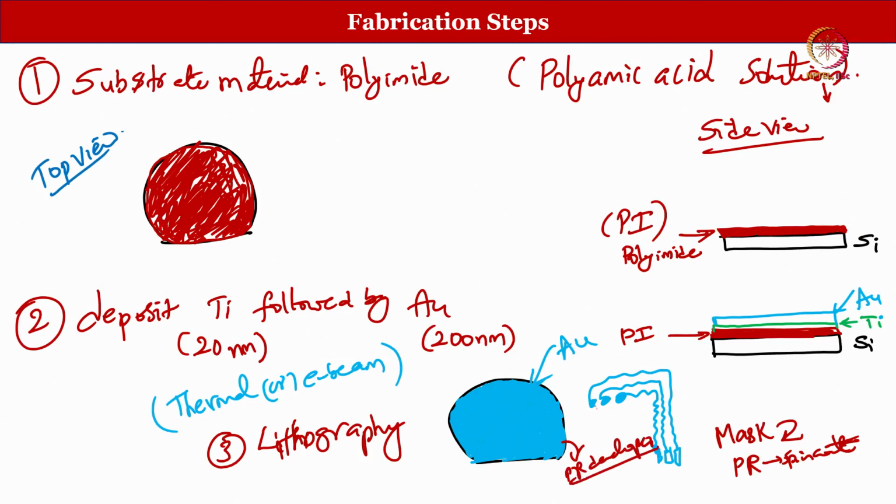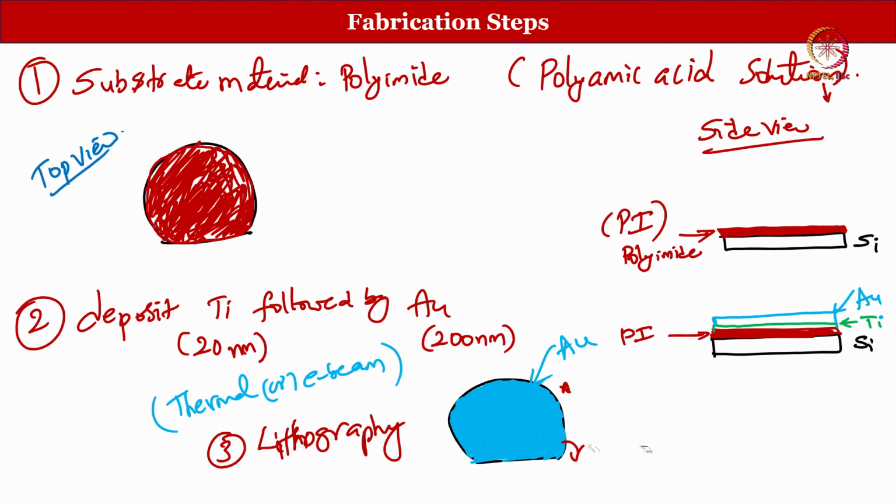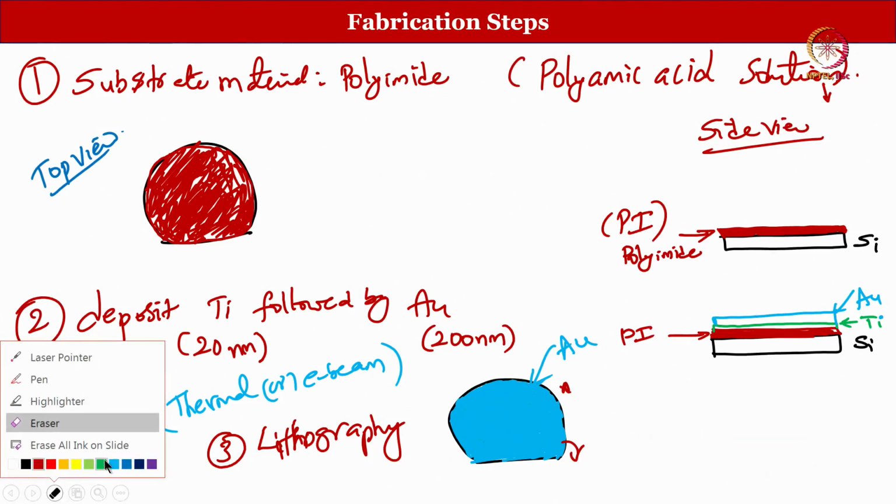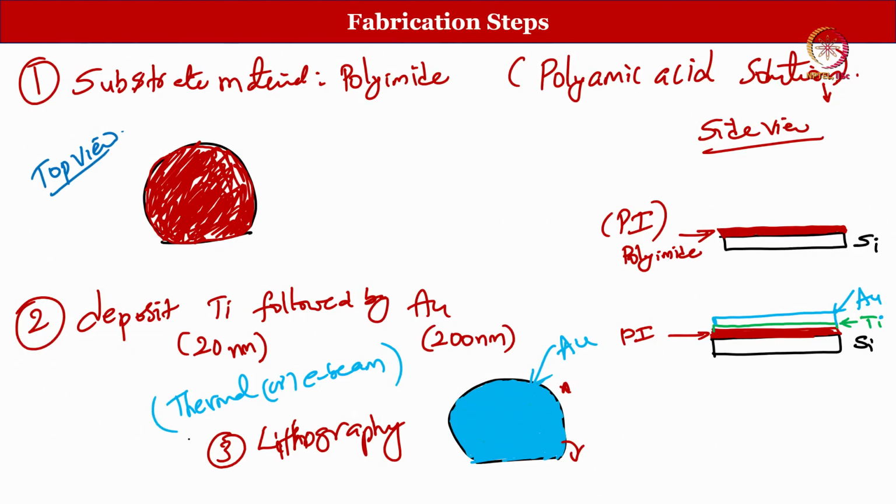According to the nature of the mask or the nature of the photoresist, some areas the material will be there and some areas the material will be removed, right. So, what is left over is the pattern that you are interested in, right. Whatever pattern is left over is not on the metal, but on the photoresist, right.